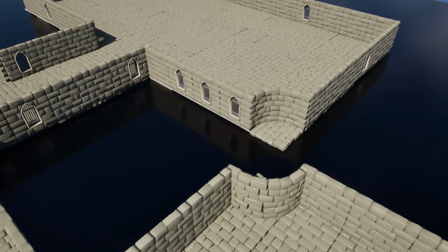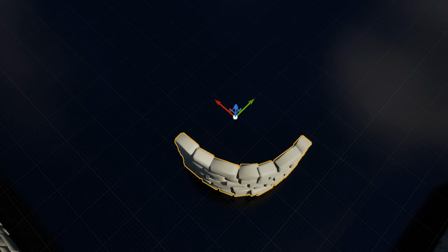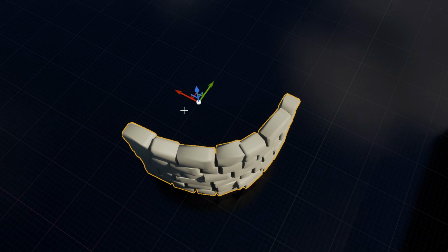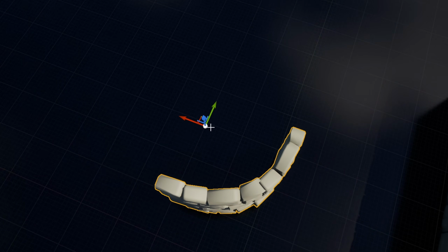Now, if you're wondering how this is angled, if we take a wall here, you can see this wall happens to go in -x and -y from the middle point. So that's how this one is designed. If yours is going positive, you might just need to add a transform points right before the static mesh spawner to rotate all of them 180 degrees, whatever yours is set up as, depending on kind of which quarter of a circle you're using.